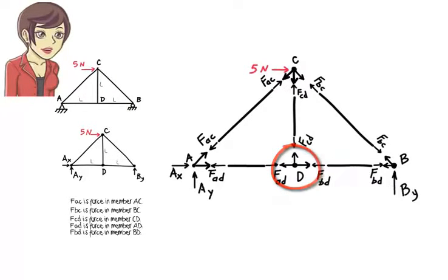Now we have the complete free body diagram for each segment. As I mentioned before, for the entire truss to be in equilibrium, each segment must be in equilibrium. We can easily see that the equilibrium equations are satisfied for each member segment. The 2 force vectors shown in each segment cancel each other.